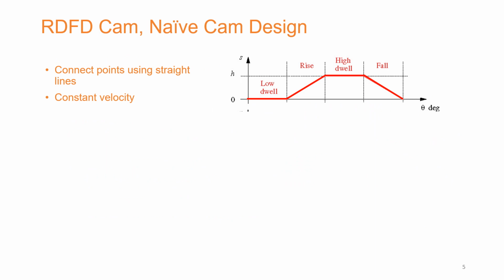So last time what we did was we connected these extreme points with straight line segments, and that you can see right over here and over here. And we were hopeful that the velocity and acceleration diagrams were going to turn out to be very good, but we were naive. Because when we observed the velocity diagram, we observed that this velocity is trying to change very quickly or abruptly, and that was visible right over here as well as over here.